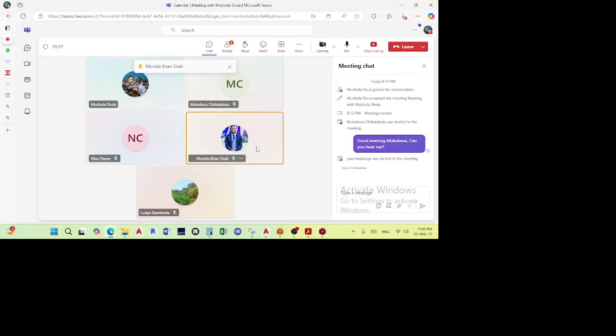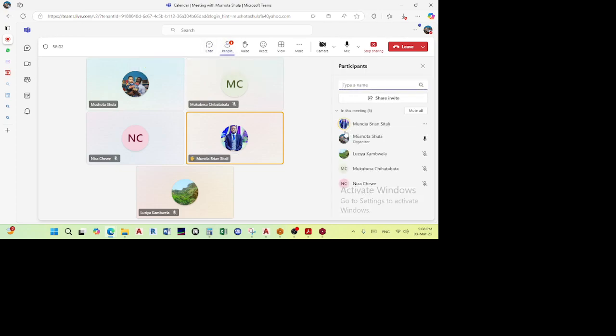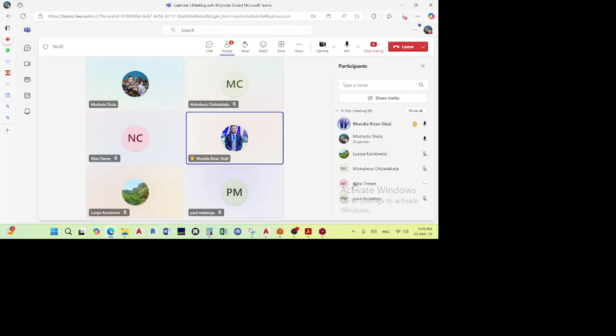Oh, Mundia's got a question. He's raising his hand. Okay, Mundia, please go ahead. So Prota is actually intelligent. When your steel column is protruding into the concrete stub column, it won't actually analyze. It will tell you, as you do a building model check, that in that case, if the stub column is maybe 1C5, it will say that 1C5 and 2C5 are clashing.